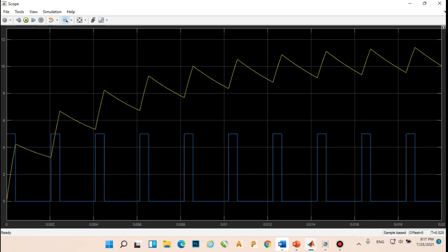If we see, our signal will increase with a PWM signal with 20% duty cycle, and with PWM at 490 Hz frequency. And the rising time is about 10 milliseconds, about 100 Hz. It's about the cutoff frequency. The voltage is about 10 or 11 volts.